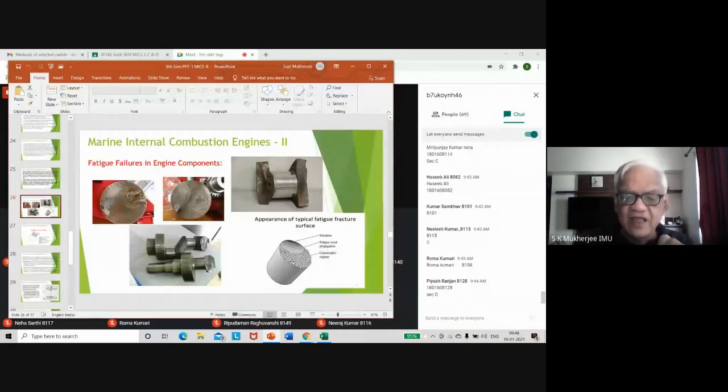If you bend it, this side is compressive, this side is tensile. What about right angles to the surfaces? They are a neutral axis. So the oil hole can be made there. And that is how you minimize the stress at the region of the oil hole, in spite of claims being made that the shaft has failed from the oil hole.